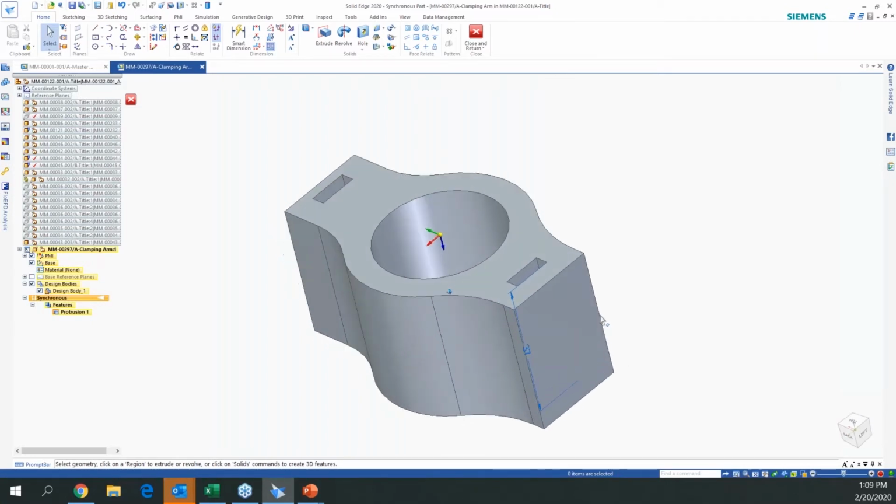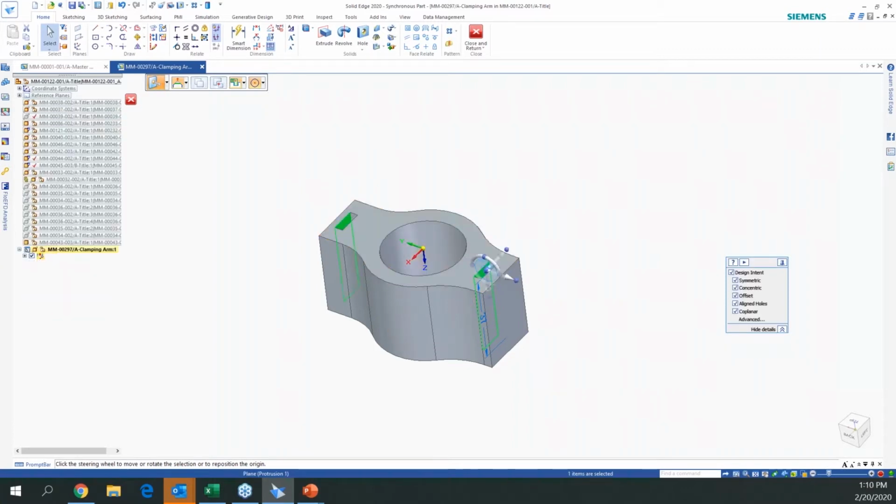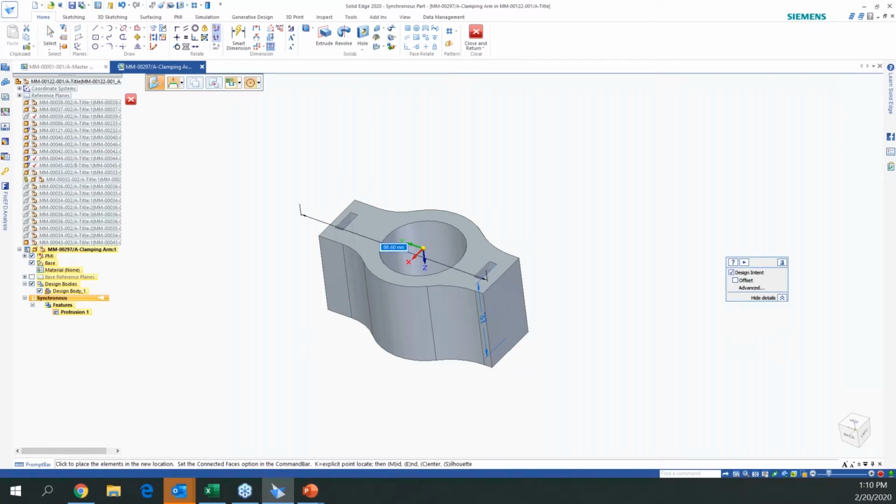Now let's just rotate my part around. So now I want to build onto this bracket. And let's go ahead and select this, because next thing I want to do is I want to create a nice little cutout in here. And I'm just doing it right on the fly as I'm selecting a couple parts. And I'm just going to turn off my offset because I'm not doing any offsets. I want to go ahead and drag this surface across. So you can see now I've created a nice little cutout. And Solid Edge will recognize that cutout, which is really nice. All right, that looks good.